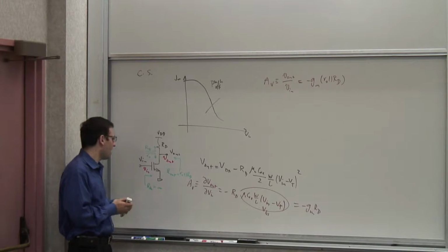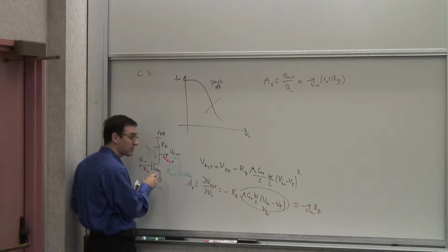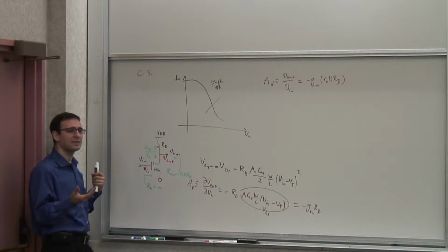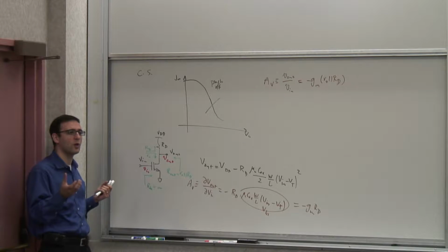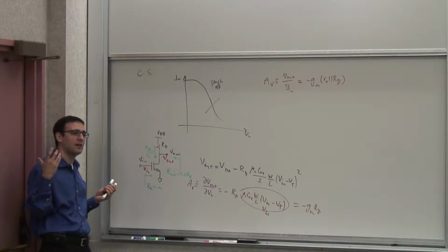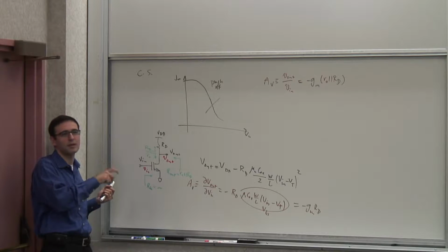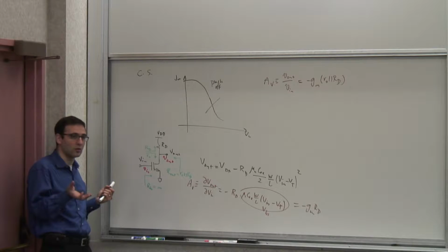Now we said, well, in general, if we are interested in knowing the behavior of this stage when you have a resistor in the source, the general resistance of RS. Now, in practice, in many cases when you are designing MOS amplifiers, you don't use resistors a lot. And the reason is as follows. Because first of all, in the basic vanilla CMOS process, you don't get very well-controlled resistors. There are variations of the process that allow you to get resistors, but they're a little more expensive. Nowadays, a lot of MOS processes have good resistors, but some of them don't.